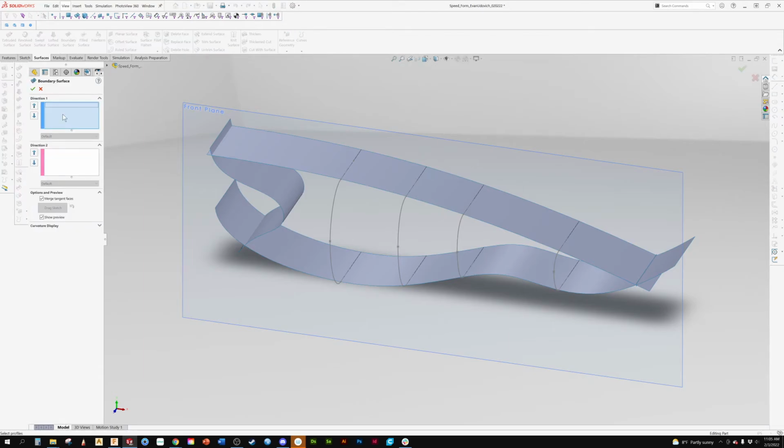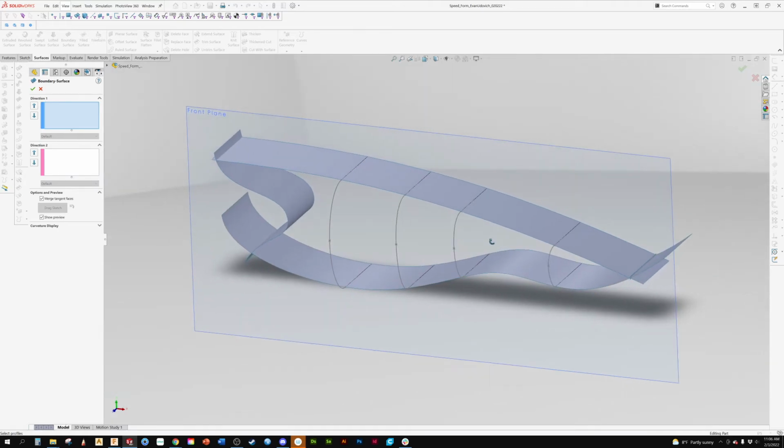I won't get into too much detail, but when I'm doing 3D modeling, surface modeling, I don't normally ever use a lofted surface. My primary ones are to do boundaries and to do fill surfaces as a primary feature tool, and then secondary I'll use swept surfaces and revolve. I just find it gives me a more robust and better model.